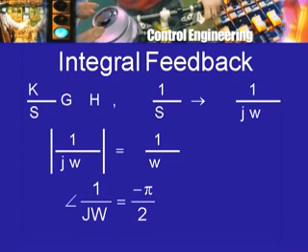So in other words, the loop transfer function gain at very low frequencies is going to be very large. It is not going to be some finite constant. In fact, it is going to increase as you approach 0 from above. That is, as omega tends to 0, you consider smaller and smaller frequencies, the gain will be greater and greater. So that was one mistake.